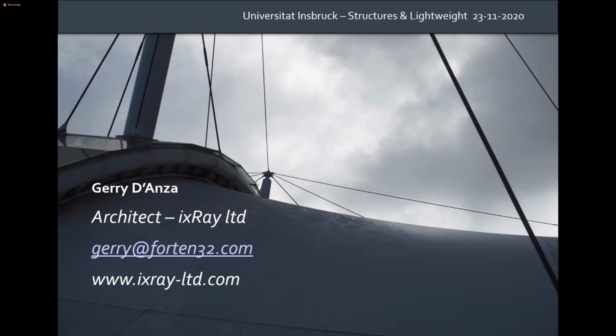So a tensile structure does not exist if we do not have a pre-stress field. It's not only geometry. We are used to designing something with concrete or with steel as architects, where we design it and we know that it's going to work. With membranes, it's not like that. We need to go through this form finding process.